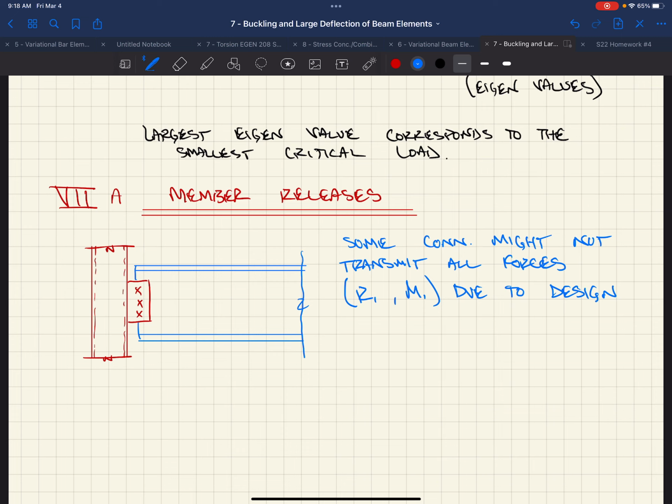Yeah, your eccentricity of these bolts is probably 3 inches. If you look at your shear tab connection, right, it's 3 inches anywhere, anyone you look at, and that's because at the code level, if you go much more than that, you start taking into account eccentricity in these bolt connections. It's like a sweet spot. 3 inches.